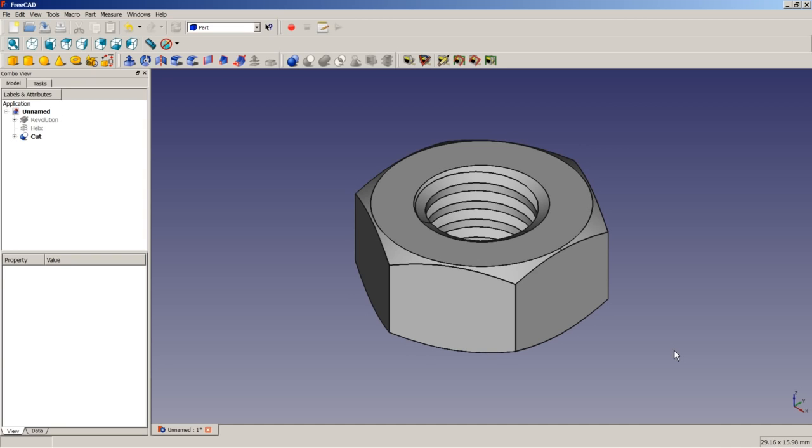In real life, this is in most cases beyond all accuracy of milling machines, measurement tools, and even beyond normally all accuracy of 3D printing. But shifting positions via placement, for example, of one of the solids by 1/1000th of a millimeter will result in a mathematical result of not being zero, and so maybe the Boolean operation will succeed in this case.